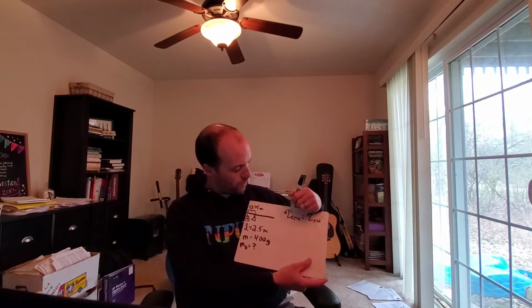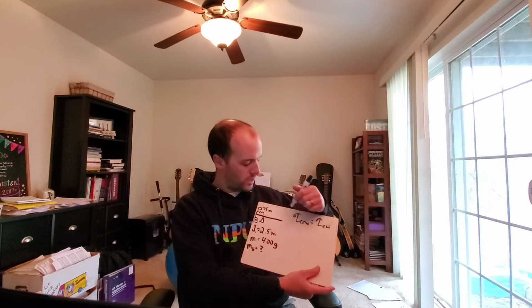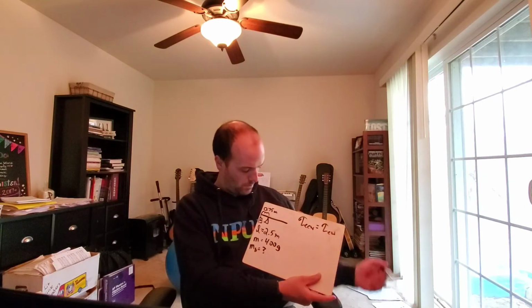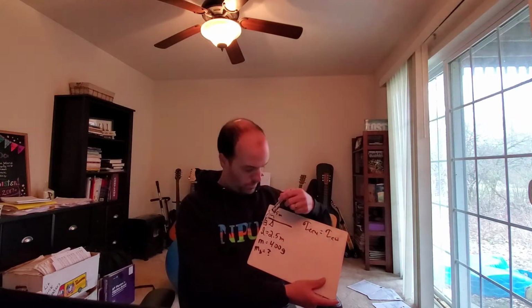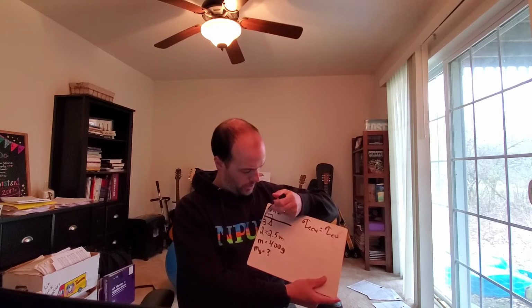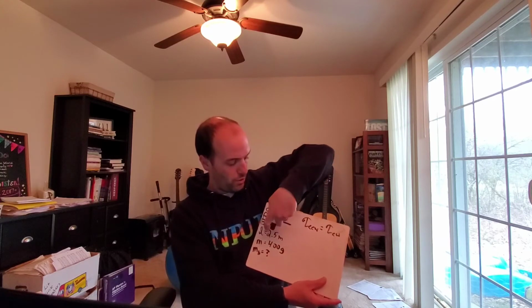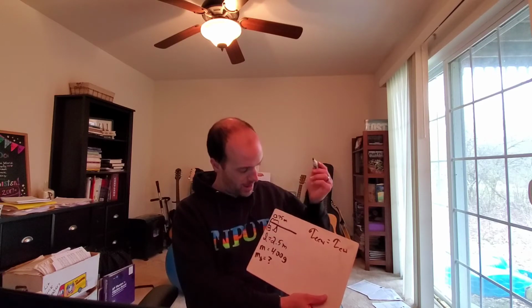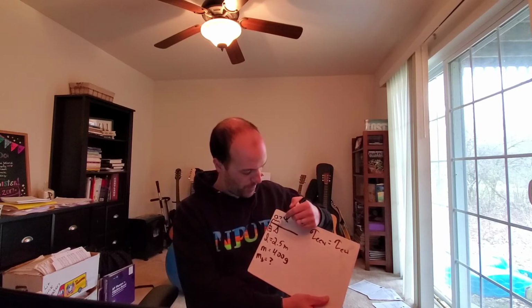What force or forces would cause this system to rotate counterclockwise? Well, it's going to be this guy right here. If this stick didn't have any mass, this force would cause this whole thing to rotate counterclockwise. So we're going to say it's the force of this mass acting from that pivot point over. The equation for torque is force times the moment arm times sine theta.